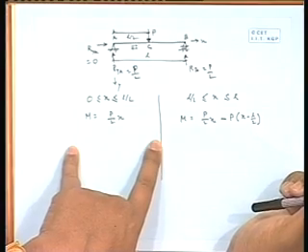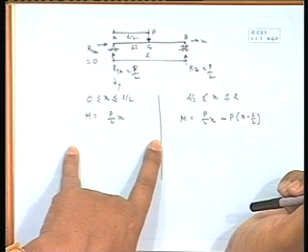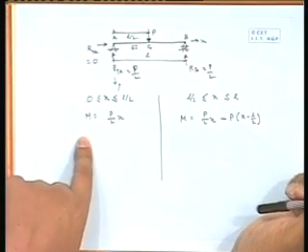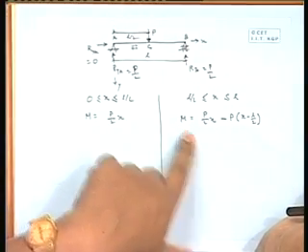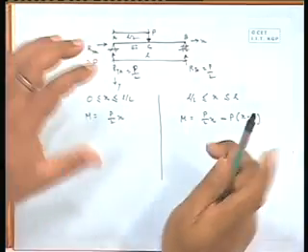For that region we have to apply the moment curvature relationship with this moment, and for the other region you have to put this moment in the moment curvature relationship. So, simultaneously for different segments you have to run it. Now, let us put the expression and see what is happening.